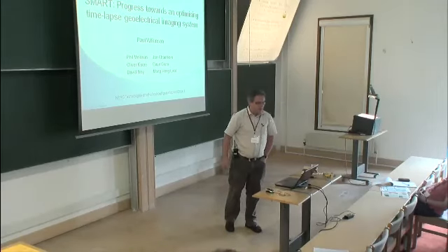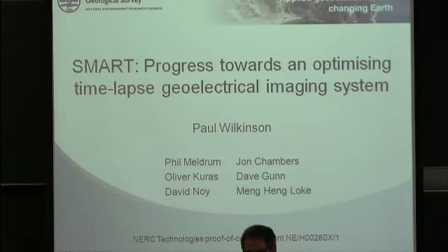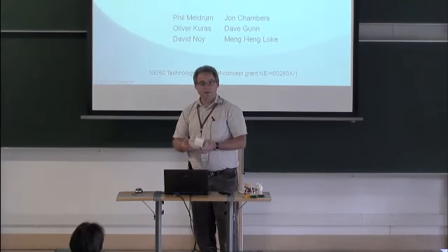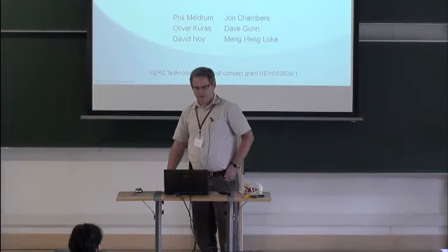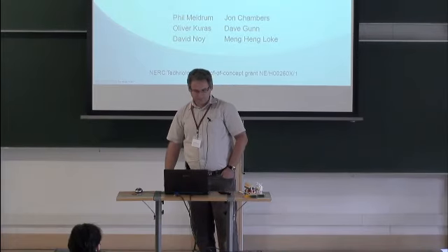I'm going to talk about optimised survey design in electrical resistivity tomography and some progress that we're making towards implementing a time-lapse focused geoelectrical imaging system. The idea being, where you have a dynamic process within the ground, changes that are occurring over time that you're interested in, you want to focus the resolution of your instrument as much as possible on those regions.